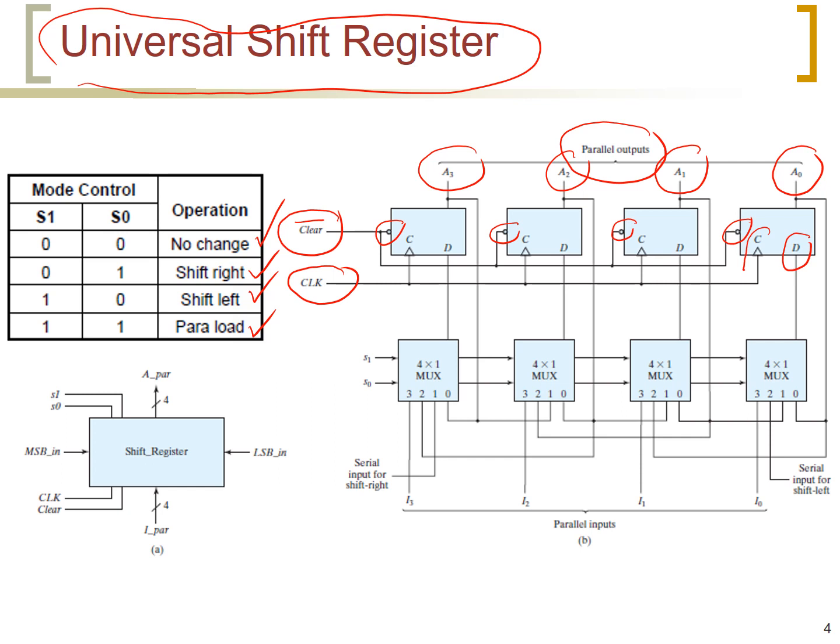To do that, for every flip-flop, we need a 4-to-1 multiplexer. A 4-to-1 multiplexer will have 4 inputs, and then it will have 1 output. It operates as follows. Now, for the 4-to-1 multiplexer, we need 2 selection lines, which we call S1 and S0, connected to 0 and 1 inputs of the multiplexer respectively.